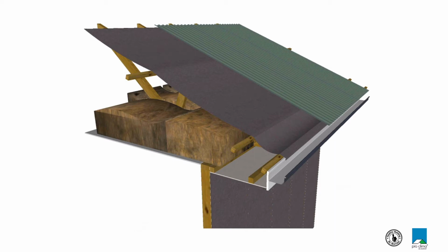So a big part of the problem is that this is the way we've been doing things, and we know that condensation is going to occur, and we rely on a piece of material that's put there largely to absorb the inevitable condensation that's going to form on the underside of the, in this case, roofing iron, but it might also be tiles.